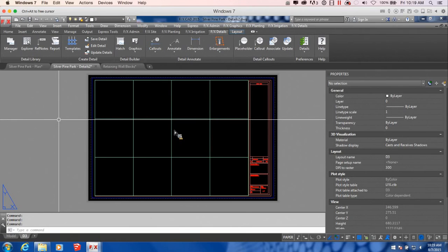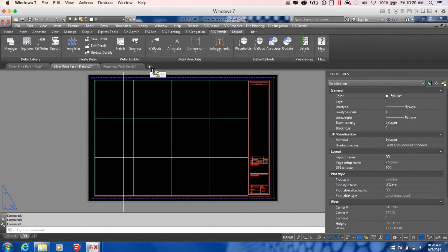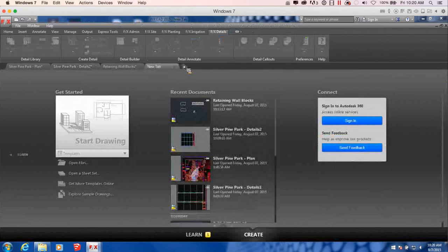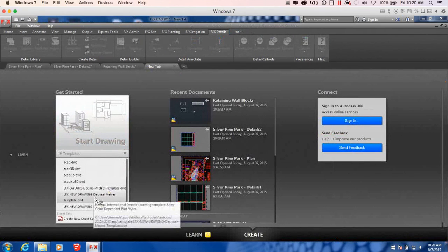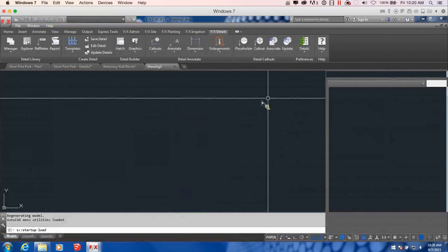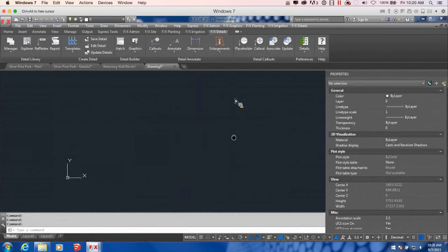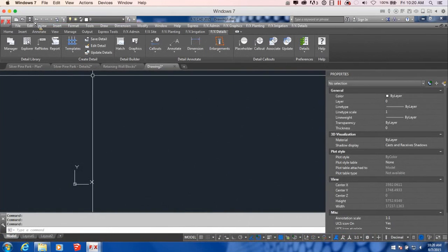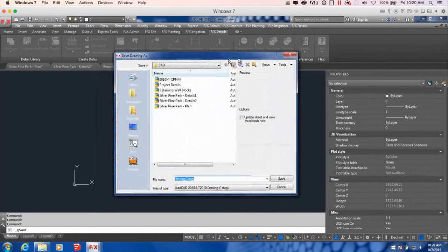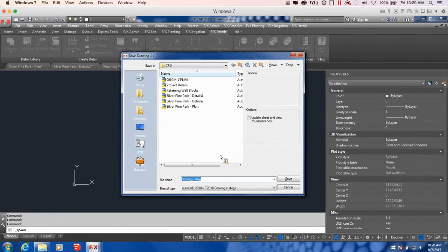And especially for the process that we're going to do, I'll go into it, but we're going to use the batch save option. So I'm going to want to save my drawing to be able to access it later and re-batch save as necessary if I need to make any adjustments through the process. So I'm going to open up a brand new drawing in millimeters, or inches if you're in imperial. And I'm going to save that right away because I'm going to do the batch save process and I'm going to put 2 details into this file. And I'm just going to call it project details.